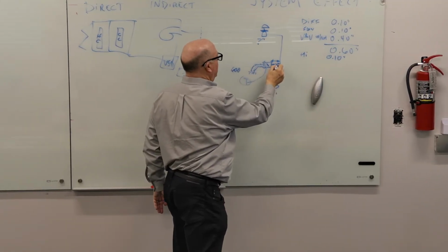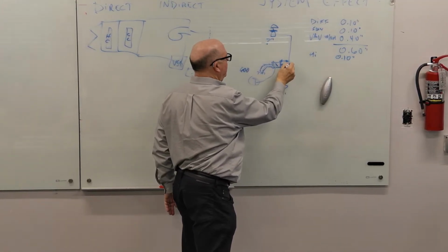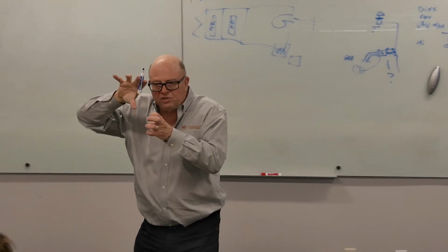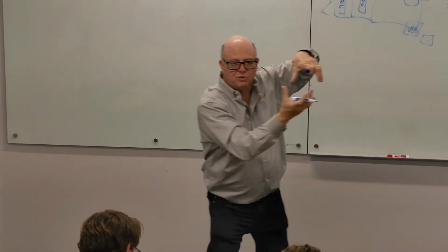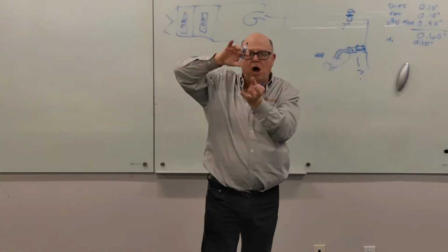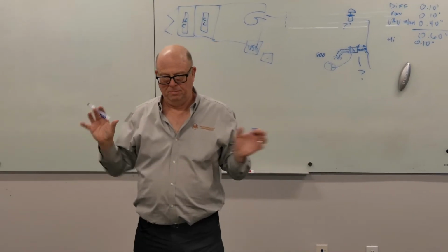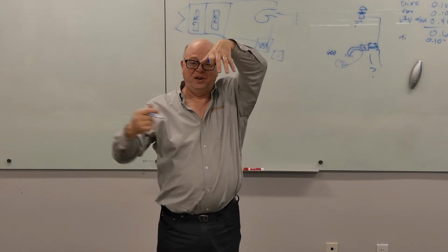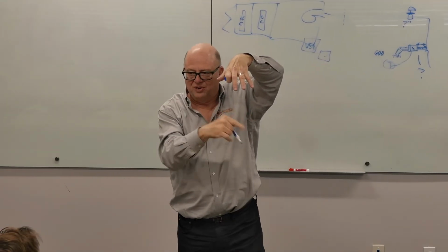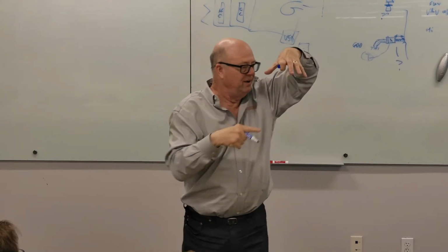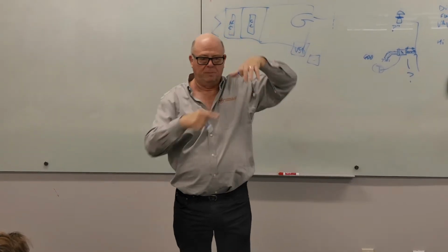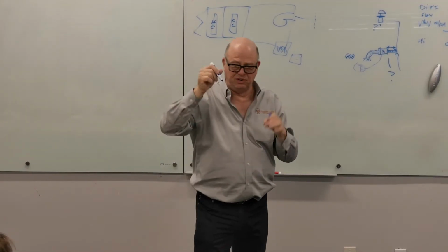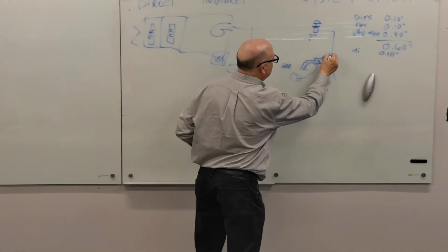Except we've got to come off of the duct, and there's a loss at that fitting where the duct comes off the main. You have a loss just making the corner because it doesn't smoothly make the corner. It's got an opening and it leaks out, as a result of having pressure in the duct pushing it. You would think pushing it perpendicular, but if we use the right fitting, it's not exactly perpendicular. You get a little bit of velocity help. Okay, so maybe it looks like this.